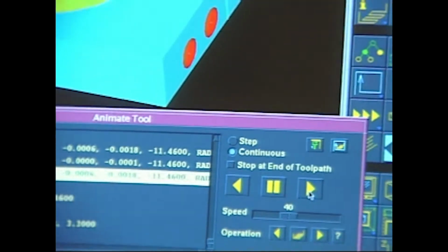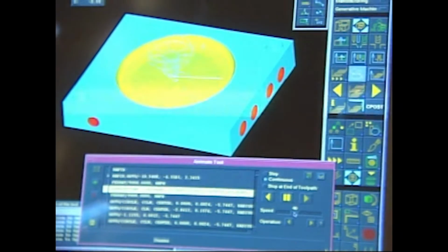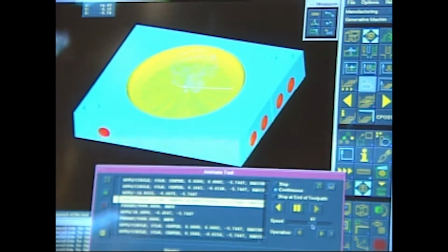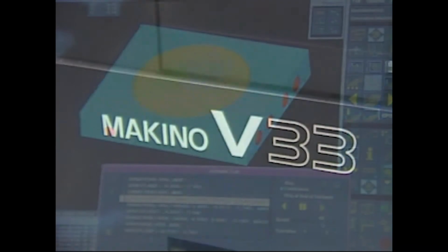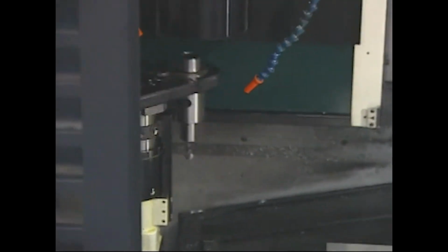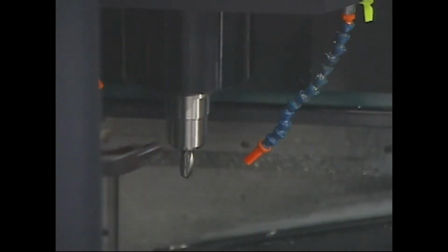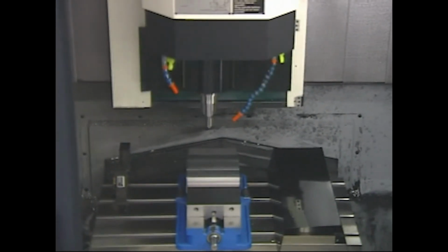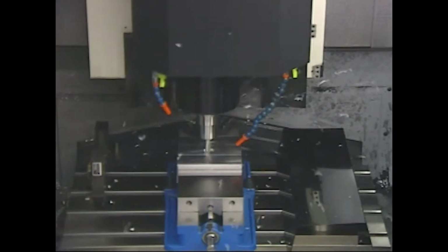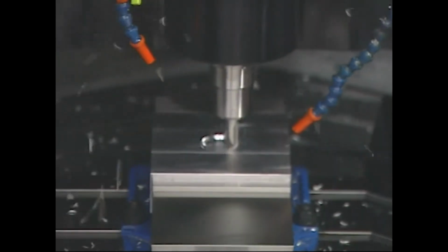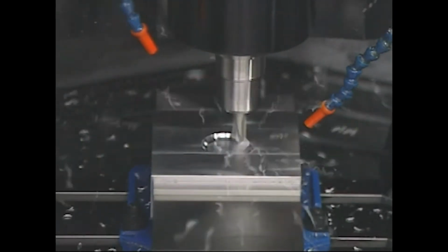After the components are modeled in the IDEAS software system, they can then be brought into the machining software where the tool path can actually be programmed to cut the specific mold detail. Once the NC program is generated from the software and loaded onto the machine tool, the program can then be run and the tool movements performed by the machine in the process of actually removing the metal to form the core cavity of the mold.